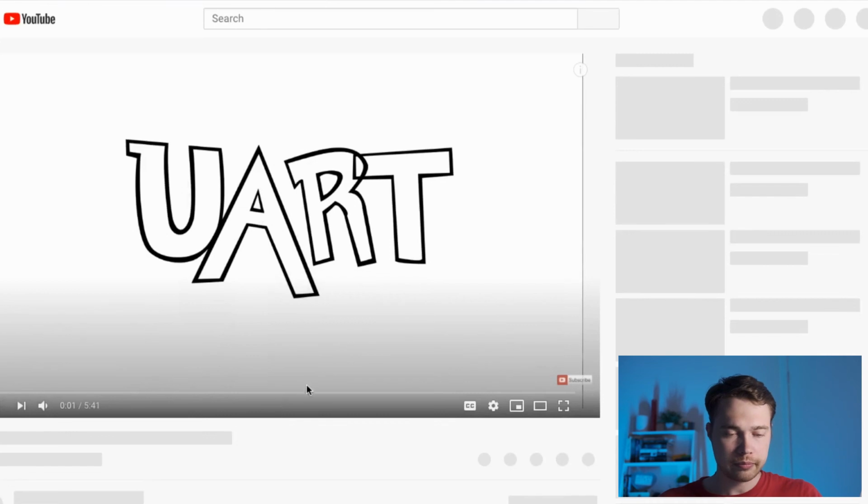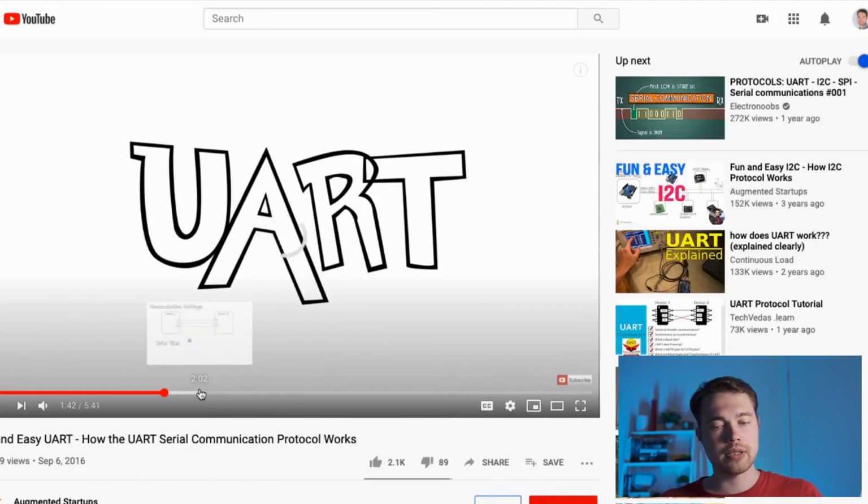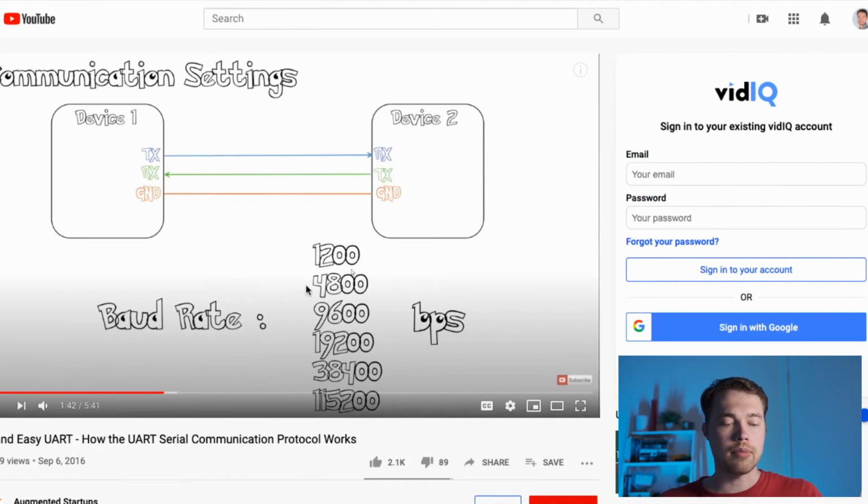My name is Fritz, and I'm going to be teaching you also about UART. So again, UART is basically the protocol, the style of communication between the parties. We have 2 devices, and you have a couple of wires. One of them is called the ground, right? And you have a couple of pins, where a pin is the output on the device. So TX of one device is connected to RX of the other device, which basically means when this guy is transmitting the data, this guy is receiving the data, and vice versa. And the ground, right? So we have 3 wires.